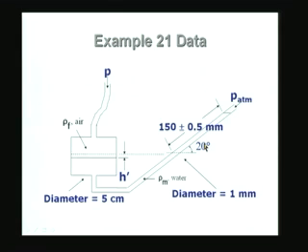So, the angle is 20 degrees, and you see the advantage of this measurement is that even though we are measuring a distance of 150 millimeters for the change in the level of the liquid in the tube, the actual height of the manometer is only this vertical distance between the datum and the meniscus level here.